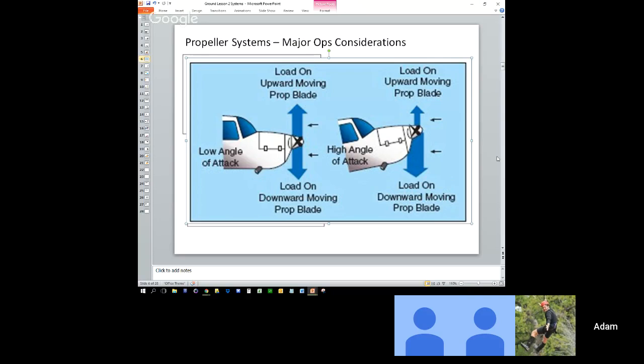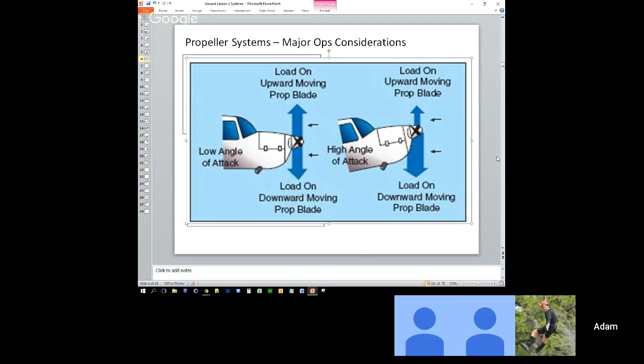So if you're the pilot and you're looking straight out of the airplane, the downward propeller blade swings from your 12 o'clock to your 3 o'clock, and then your 3 o'clock to your 6 o'clock. From that 3 to 6, the blade in that particular point of travel is creating more lift than the blade that's traveling from 6 to 12, 6, 9, 12. And that causes more lift, and it causes the aircraft to yaw ever so slightly to the left.